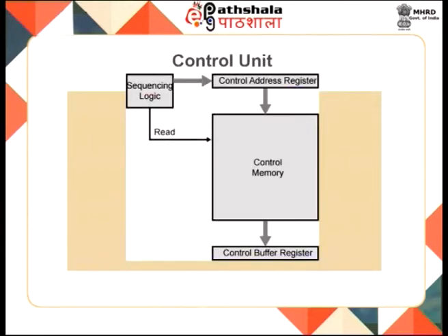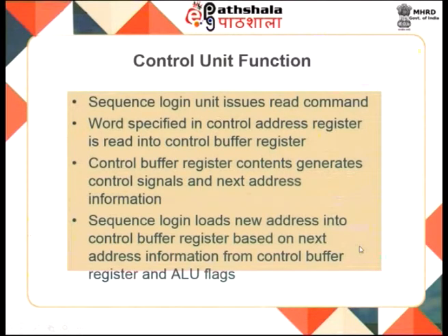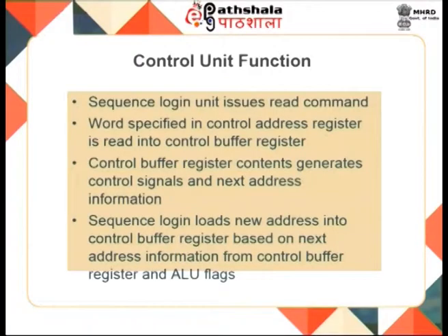So, again, to look at the control unit, having discussed the basics of microprogram control: you have a sequencing logic which will allow you to sequence through the control memory and generate the next micro instruction address that goes to the control address register, which is used to address your control memory. The words from your control memory, which is your control word, are put into your control buffer register, from where all the control signals get generated. If you look at vertical microprogramming, the words that are obtained from your control register may have to be decoded to one or more levels in order for you to generate all the control signals.